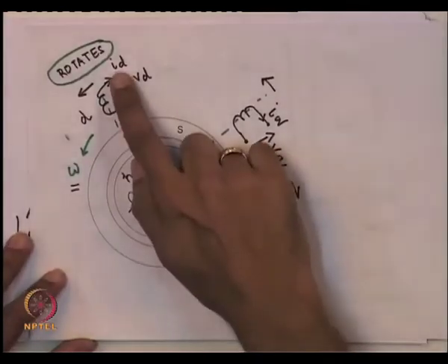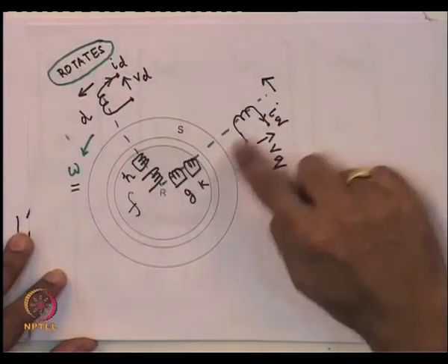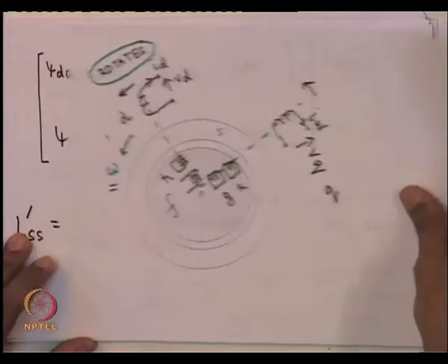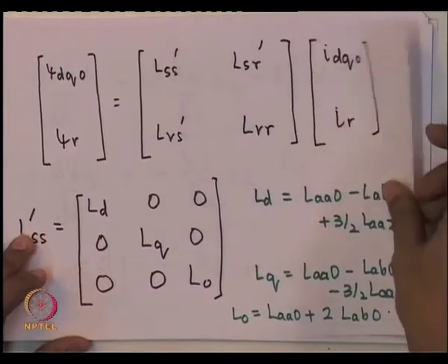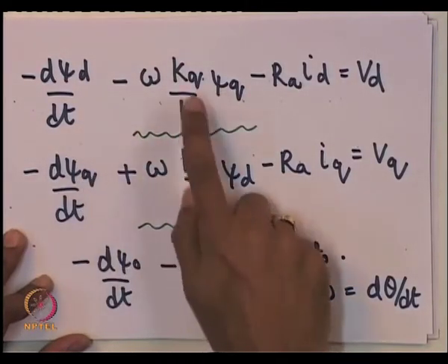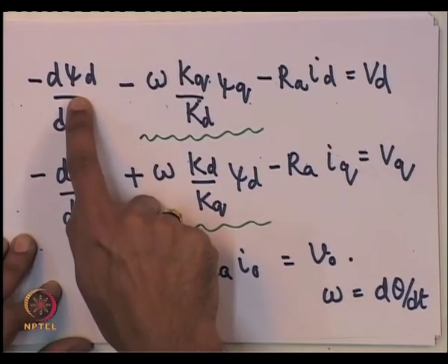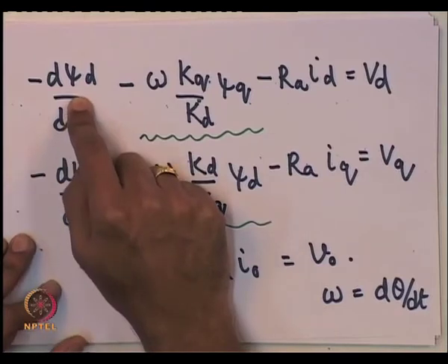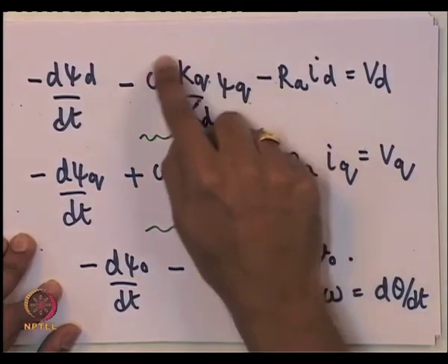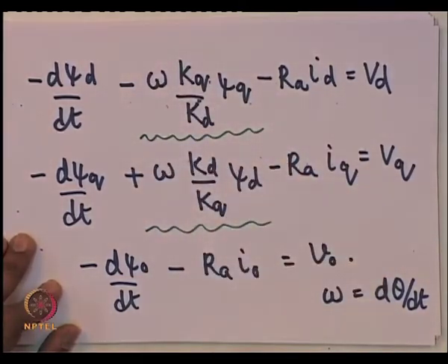Okay. So, I call this the D axis coil. The fluxes in the D axis coil are not dependent on the q axis currents, none of the currents. But importantly, when you look at the flux equation, there are speed EMF terms. So, Faraday's law, when you apply it to psi d, you have to put this extra term which comes because of applying the correct mathematics to the transformed equations.